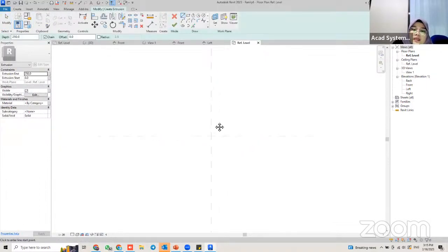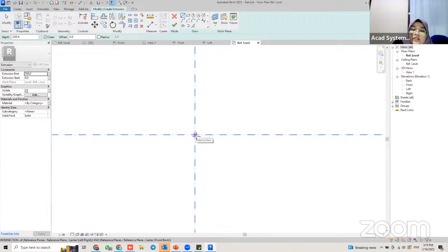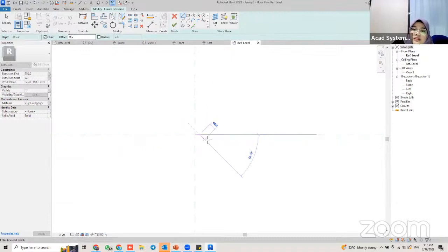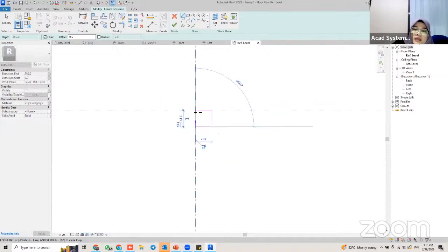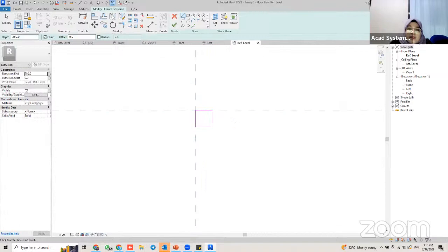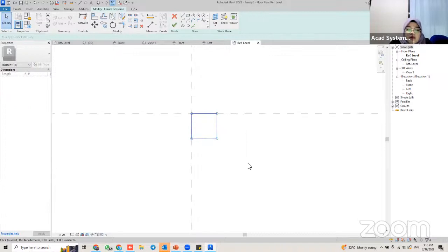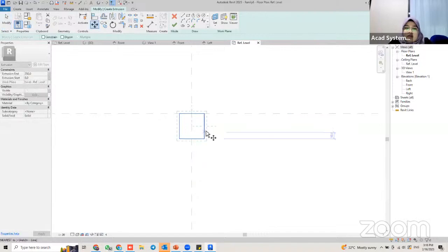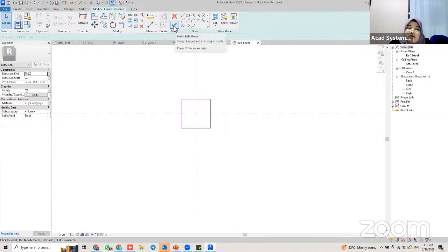Click on this one. And I'm going to create a square here using a line because I want to insert the accurate dimension. So click on this point, insert 41 for this plate size by 41 and connect this square. While you are in the extrusion command, select everything and move it to the center of the reference plate. Okay, it will look like this and click on finish.